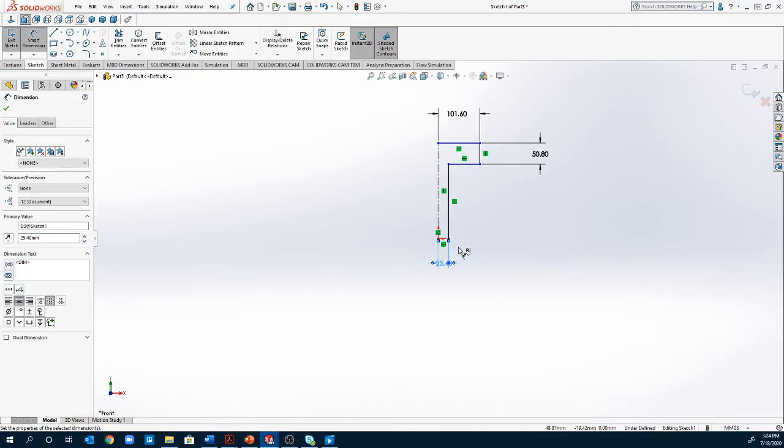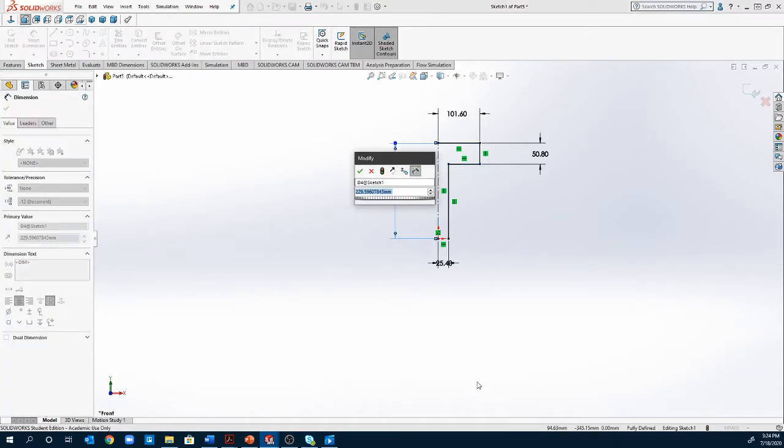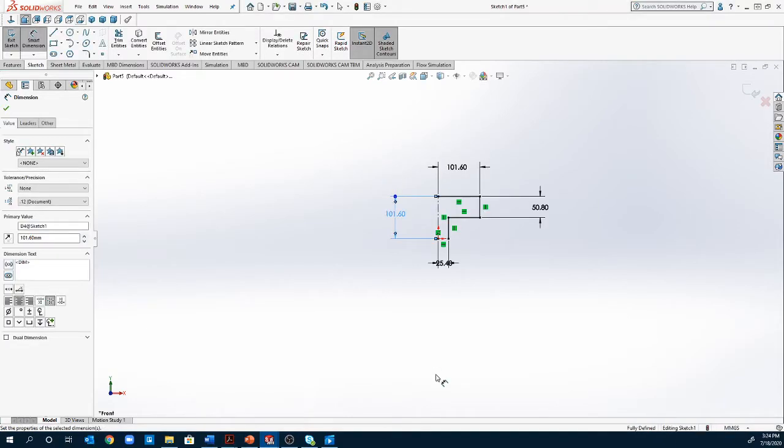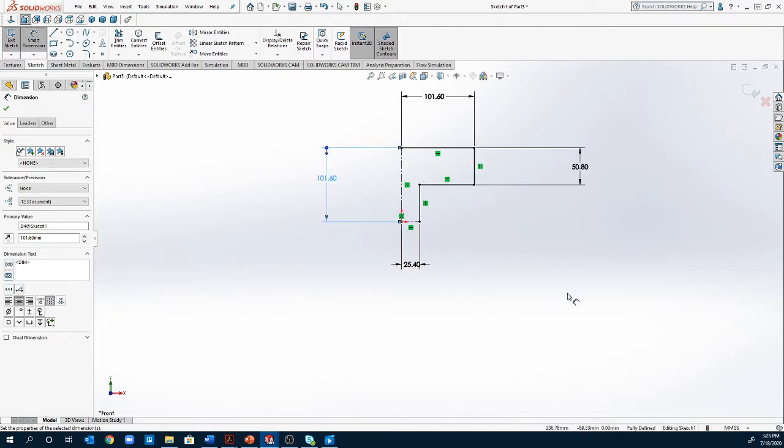And then we're going to say that the height of this entire structure, so this entire I-beam, is going to be 8 inches total, so we're going to say 4 inches. And you'll notice it's kind of short and squat, but once we do our mirroring, it's going to look right. So we need to do 2 mirrors here. If you notice, everything is fully defined now.